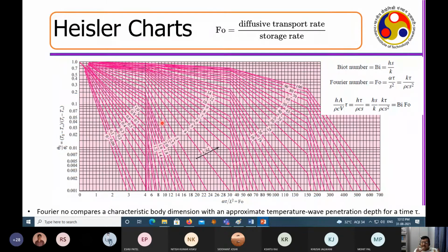But the moment you get geometries like cylinders, concentric shells, cylinders with inlets and outlets, the geometry becomes very complicated, and there you will find it hard to get analytical solutions. So you need to do smart approximations for those geometries and then combine the parameters in such a manner that you come up with plots which are specific to a cylinder, or a rectangular cube, whatever geometry you are doing.